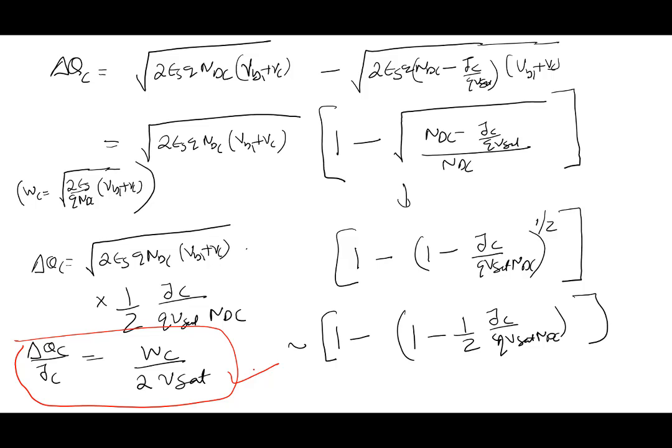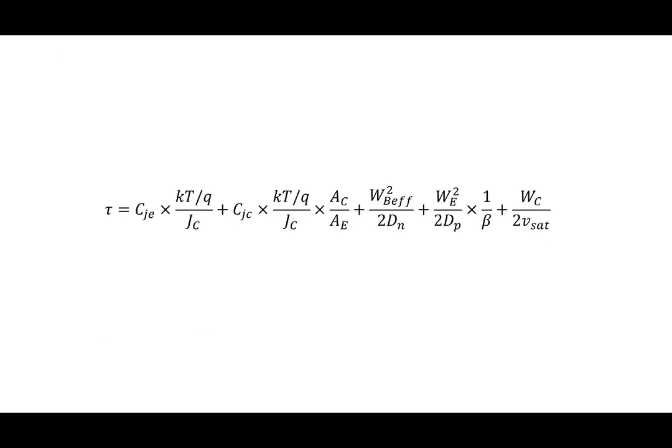All right, so let's then continue. So this then becomes the model of the delay in a BJT. And as I said, Ft equal to 1 over 2 pi tau, the unity gain frequency. A complete model.